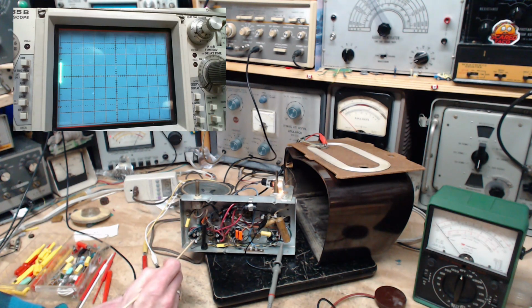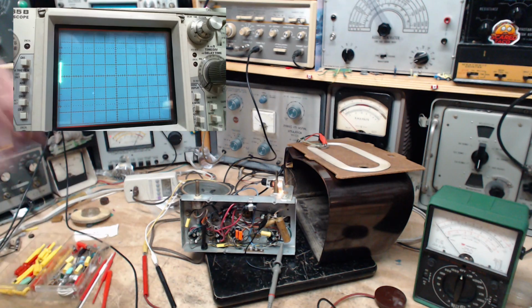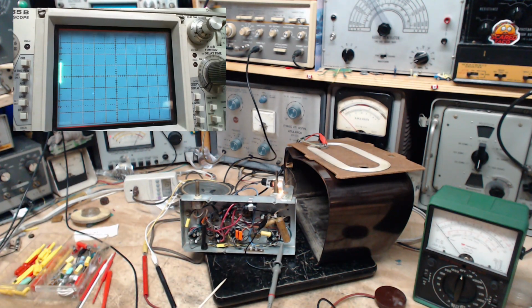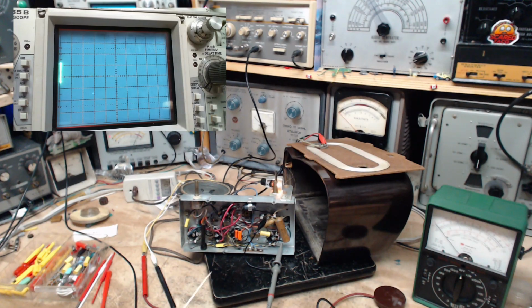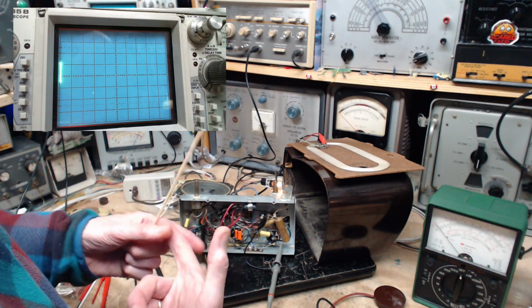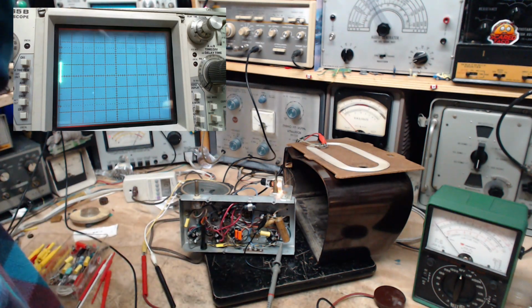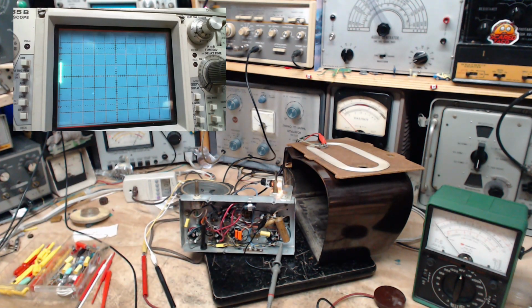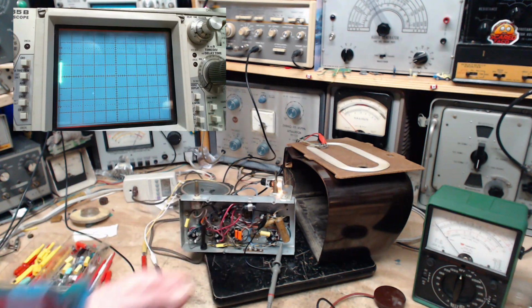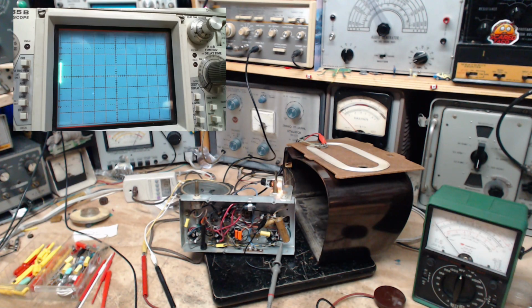This one pin here. So it could be nothing more than the tube is not in the socket absolutely correctly. In fact, I've got the radio laying on that tube. Yeah, I think it's probably just the pin shifting a bit in the tube socket, maybe from heating and cooling or other effects. Okay, not to worry too much about that. Now, the next step along the way might be to cut one leg off the capacitor and test it in other fashions outside of the radio. I don't want to do that just yet.